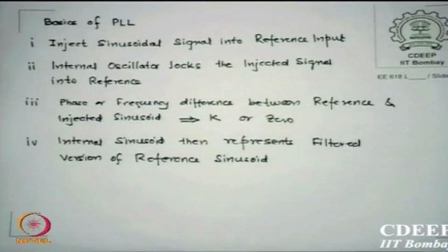They should follow this model, rectangle model. So before we quit PLL, there are a few interesting things about PLL which analog PLLs use, or analog signal processing people use, which is they inject a sinusoid signal into the reference input, which is the frequency at which you want the reference signal.